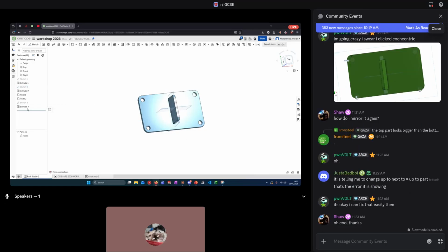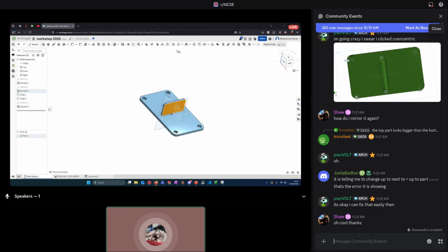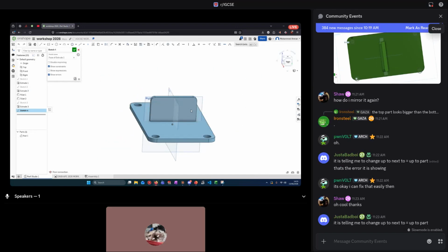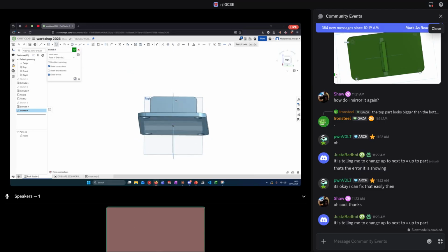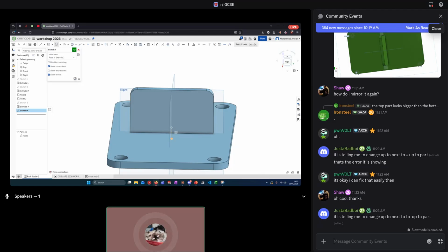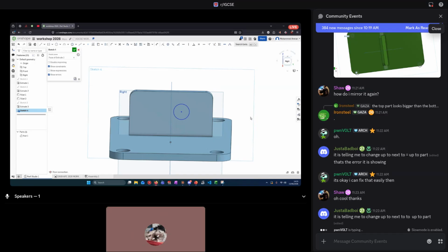Okay. So now we're going to create a sketch on this part. Right click, new sketch. So now once we have the sketch, this window should show up. We're going to draw a circle right here. We could either have it automatically constrain it to the origin to be vertical from the origin by hovering over the origin and then going up slowly and then drawing the circle. Or you could just draw a circle anywhere and then come here to the vertical constraint, press on the center of the circle and the origin. So now it's vertical with the origin.